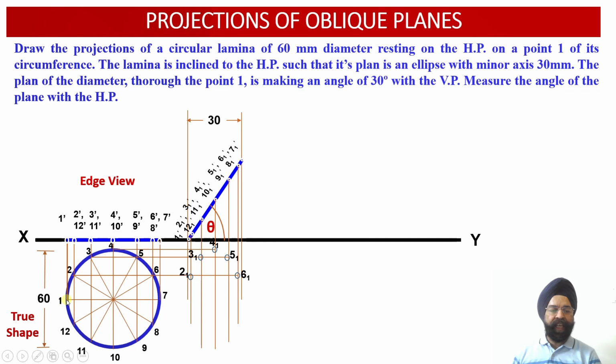Similarly, there is going to be one horizontal line corresponding to the points 1 and 7. So this horizontal line, wherever it intersects with the vertical projector from 1 1 dash and 7 1 dash, these are the extreme points over here. 1 1 dash is this extreme, 7 1 dash is this extreme. So below the 1 1 dash, the point of intersection with this horizontal line will provide 1 1. Below the 7 1 dash, we draw the vertical projector line, and its intersection with this horizontal line originating from point 7 provides us with the location of the point 7 1.